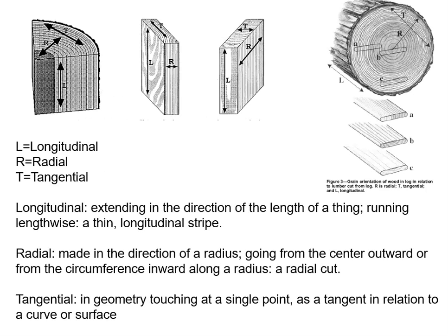Okay, just a quick review of some vocabulary, very important to describe the geometric properties of timbers and boards. So we have longitudinal, radial, and tangential. Longitudinal is cut along the length of the tree trunk. Radial would be coming from the center. So if we cut a cross section, like here, we're looking into the longitudinal axis. So this is the longitudinal axis in this direction.